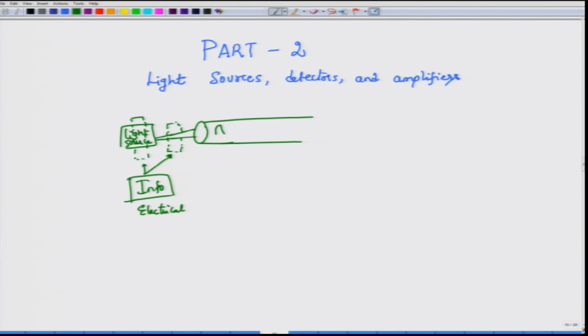A simple digital modulation would look like this. Whenever this is written, it means that this is a symbol 1 and light is present, or a light pulse is transmitted, and when you do not transmit anything, that corresponds to 0, and no light pulse is transmitted over the appropriate symbol duration. So, a sequence of pulses could represent the information in the form of a binary representation, and that binary representation itself could be coming from the actual message.